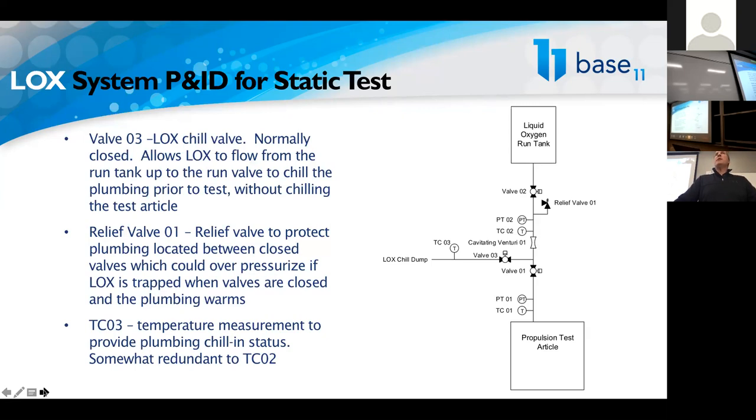By the same token, to further improve the situation, you have other options, right? You can rate limit how quickly your valve closes. So most of the time what we use are pneumatically operated ball valves.